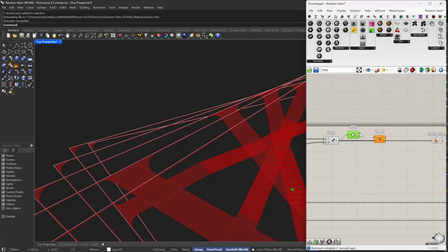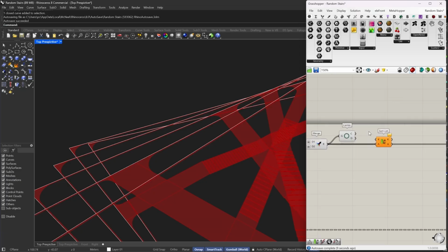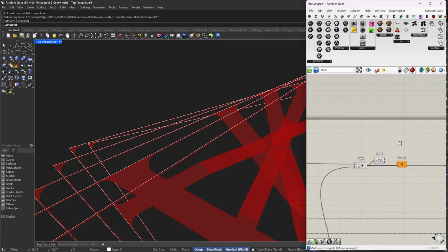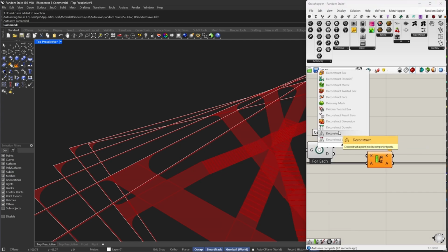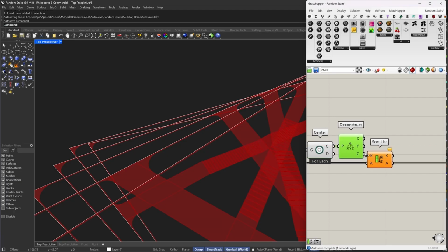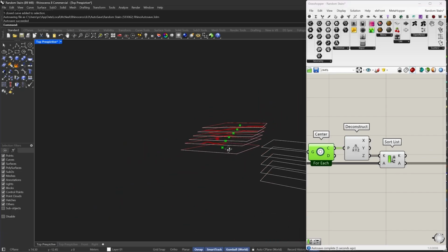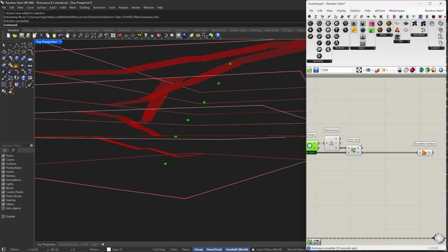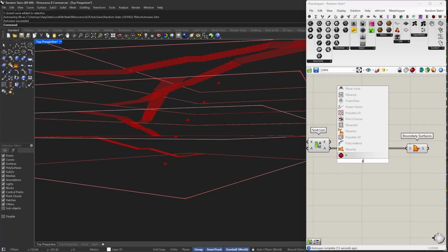By the way, I want to lower this, so I'm going like this and then click again. Again, let me tell you this. I think you know it already, but it's Alt and then I will click in here and then I will click Alt again to make it like this. And deconstruct, of course, and I'm going to sort based on this. So what I have done is basically organizing them by height. So right now I have 2 in this level and 2 in this level, and after that I'm going to make a partition list.